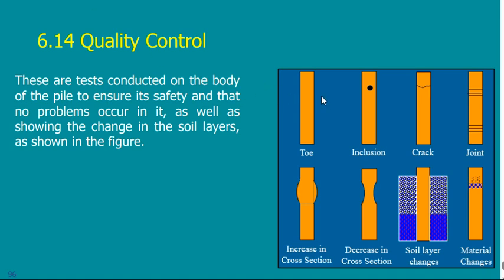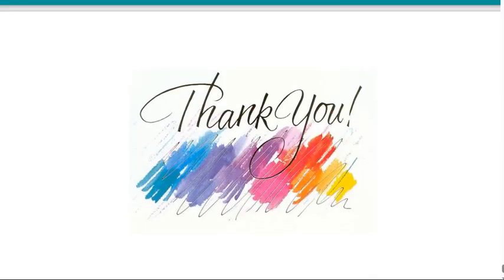All piles I can check, because it may tell me if the pile has inclusions, cracks, joints, a decrease or increase in cross section, anything related to the pile or sometimes related to the soil next to it. They can tell me something like the sonar, the ultrasound that you do when you go to your physician, but we do it on the pile itself. So this is also very important.